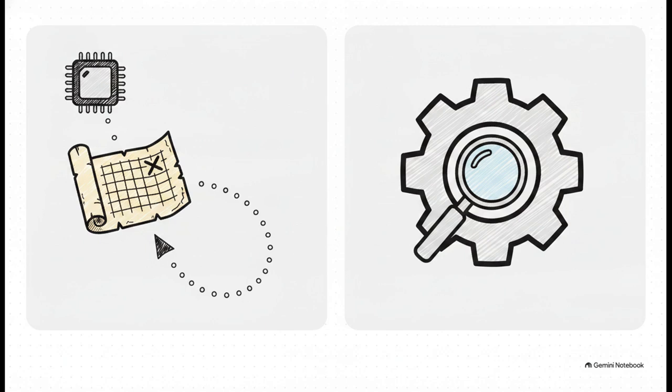Indirect addressing is kind of like giving the microprocessor a treasure map. The actual memory address where the operand is located is specified by the contents of a register pair. Contrast that with implied addressing over on the right. Here, the command is so incredibly simple that the opcode itself implies the target. For example, CMA simply complements the accumulator. The address is just baked right into the command itself.